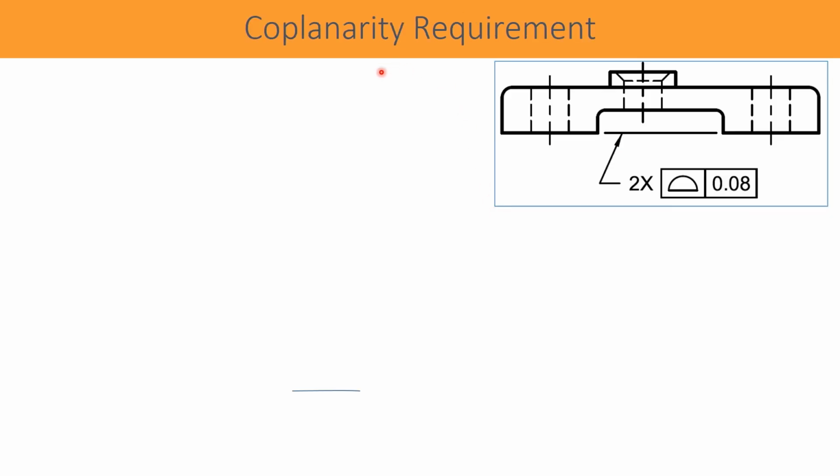Let us discuss now the application of a profile. In this drawing, a profile tolerance is given for two surfaces, 2 into, then a tolerance frame. It means profile of two surface is given within a tolerance 0.08.